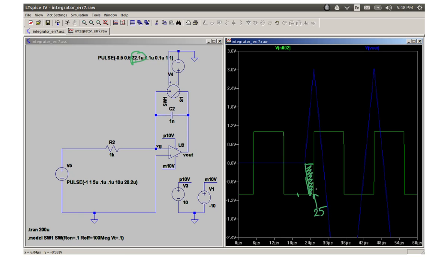It was able to get this much area, which was basically a small number, and then it subtracted this area. It's a much larger number, and then it sort of stayed there because this one equalized that one. But the initial area you got set your top point. It didn't get to 5 volts, it only got to 3 volts because your delay was off. So you can get various offsets depending on where you turn on this, or basically release the switch.